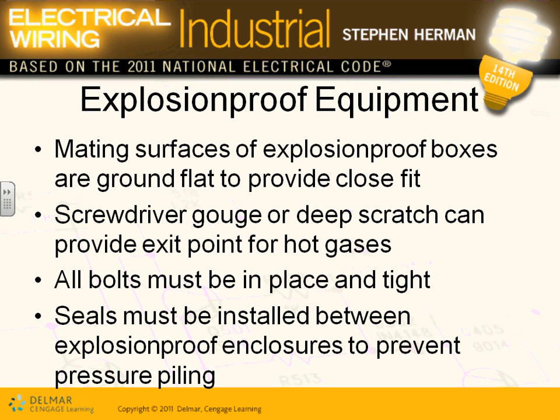So dealing with these boxes, if you go with your screwdriver and make a hole or a niche in a box, you just screwed up the listing of this box. That's a big deal. A screwdriver with deep scratches, if you have a deep scratch, can provide an exit point for the hot gases. You don't want the gas to get in and the hot gas from an explosion to get out, right? So you don't want to make any holes or niches in these boxes.